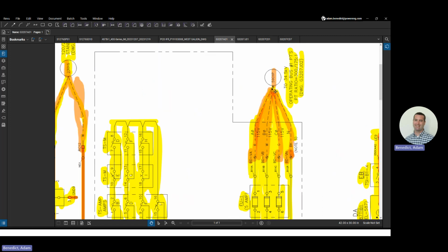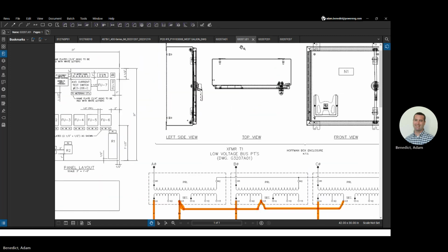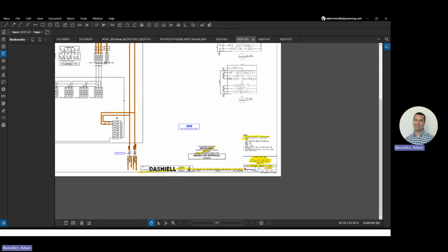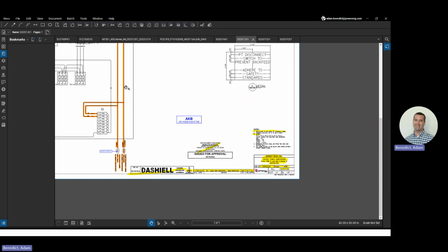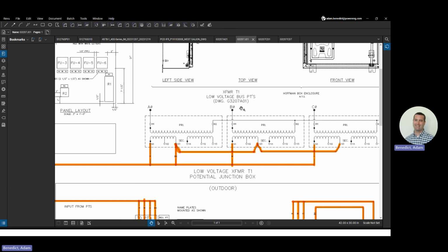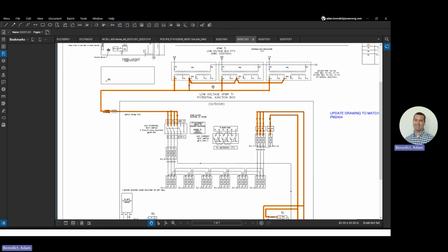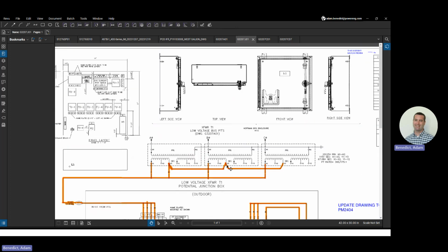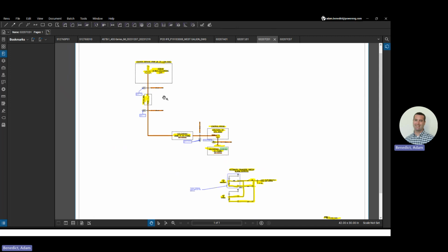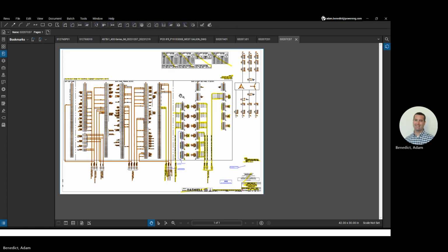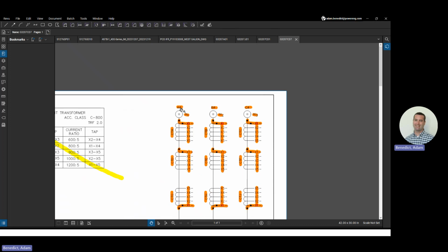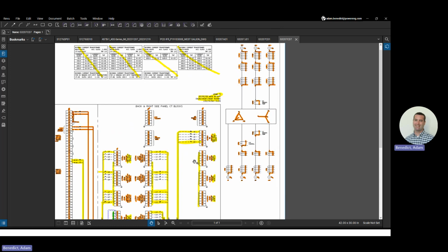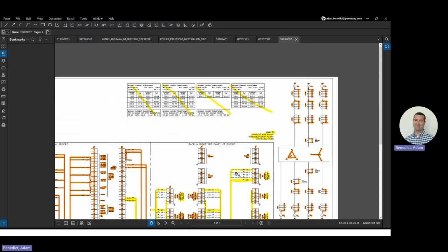And then we're looking at our VT connections as well. Their VTs, they don't show on the AC schematic, but they do show it on their wiring, their junction box wiring. So I did pull that up. And here they just have the ABC labels. This is a back check, so not everything is actually, sorry. They used the wrong standard, so I didn't finish checking that. That's why it's not highlighted. And then here's an example of some of the wiring, and this is showing the highlights where I was making sure this matched the schematic, and then once I checked that, I was able to check the wiring as well.